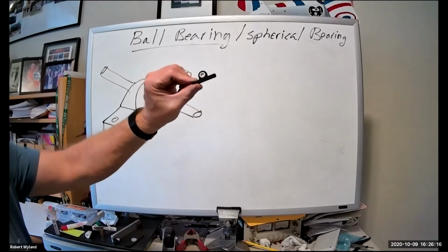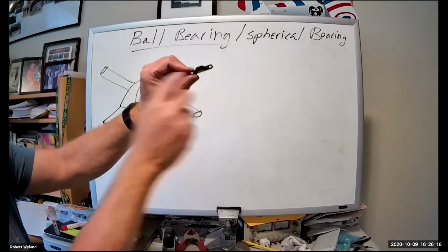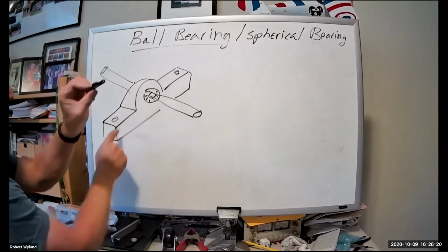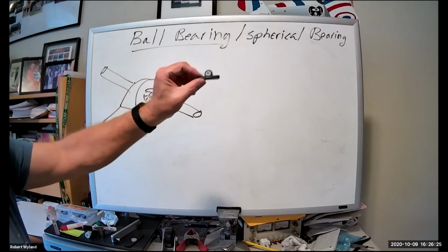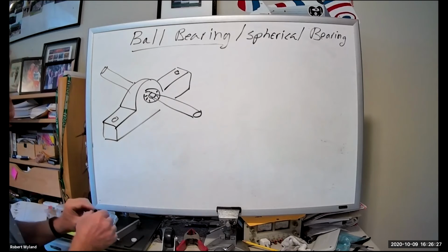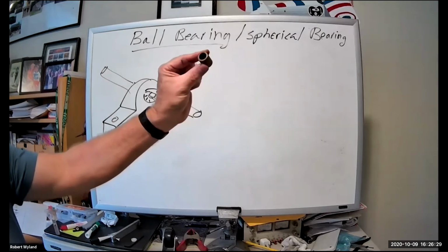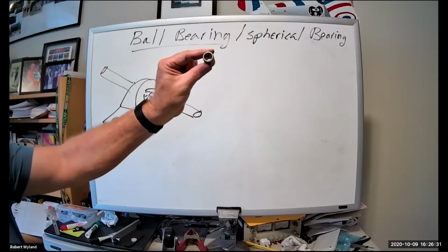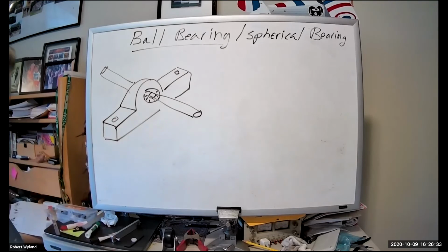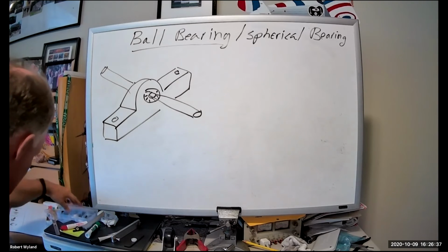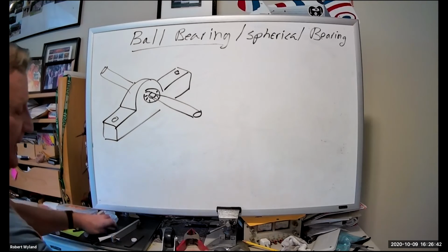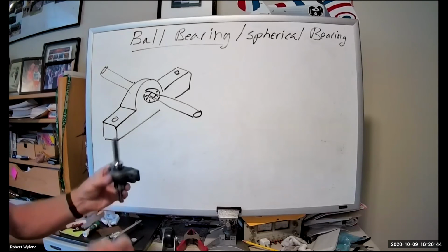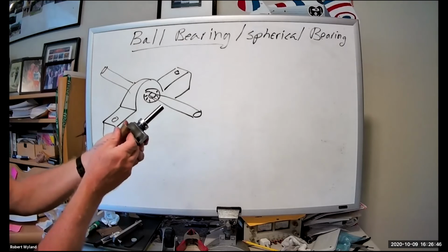And it's just the way that they hold it. You've got the mounting holes here. This is the pillow block part. There are other ways to mount bearings. Like I said, this by itself is a bearing. Generally, you would press fit it into some part and it would just live there. And in fact, on this plain journal bearing, all they've done is take a pillow block and press fit one of these guys in there.